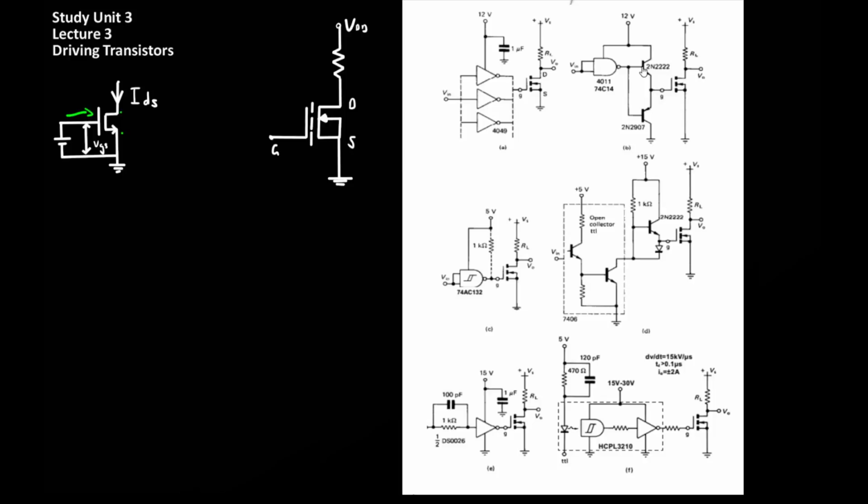on this device. The reason this circuit speeds up the switching time significantly is because the current provided by the CMOS gate is effectively multiplied by the beta of the BJT transistor, which then supplies that current to the power transistor. The primary advantage of this circuit is that the switching times are now no longer limited by the CMOS logic used, but instead by the specifications of the BJT transistors used.